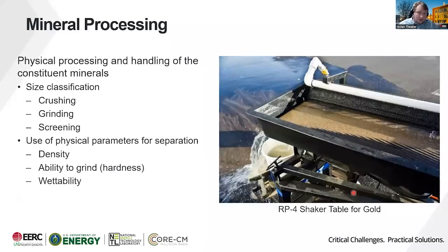So in mineral processing, the physical processing and handling of these constituent minerals is what that means. And the size classification on this: crushing, grinding, screening. This is just taking big rocks and making them smaller, and then separating them based on their size. No chemical impact is associated with that. It's just crushing and grinding.